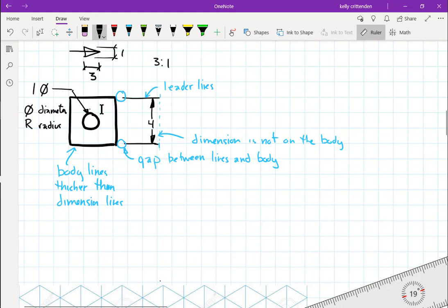There are other levels to this also. If you actually were making a document to send to a machine shop, don't ever give them just "you want 1." You need some amount of tolerance. Can it be bigger than 1? Can it be smaller than 1? To make it exactly 1 is extremely expensive. To make it 1 with some tolerance is kind of normal. So what do you really need? How close to 1 do you actually need?